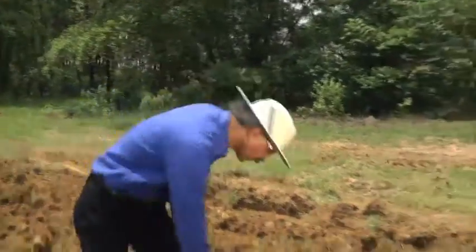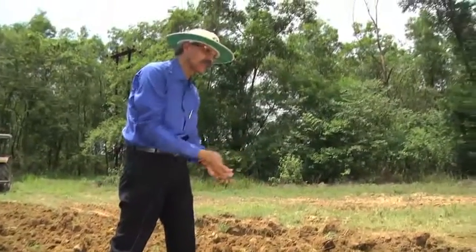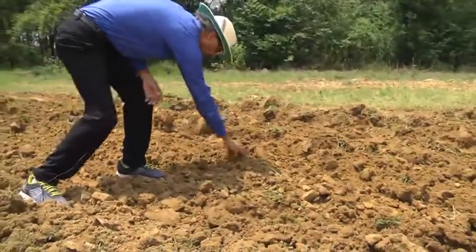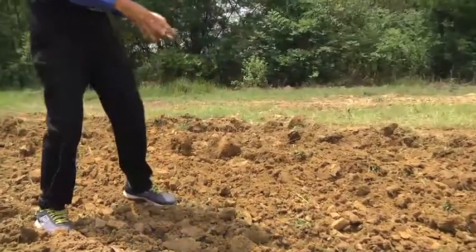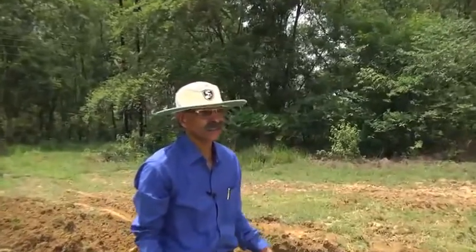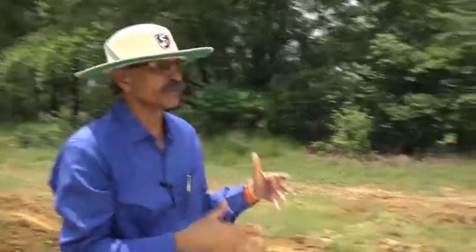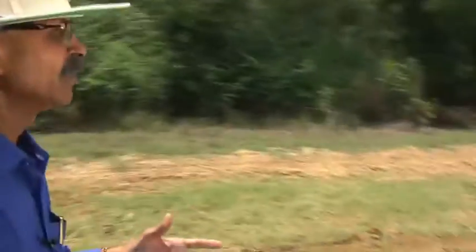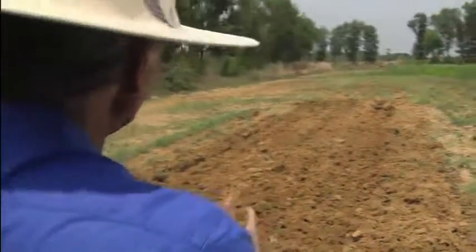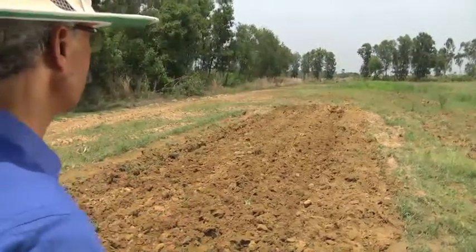Now, definitely this particular implement has broken the soils and the big clods, but you can see yourself that it will definitely require at least twice operation of this, and then at least a planking, that means smoothing of the soil, then only the field will be ready for seeding. But this has a separate requirement when the field is virgin and it has been operated by either a moldboard plough or a disc plough, where the soil has been inverted and then it needs to be broken to smaller particles, and that is why you require this particular equipment.